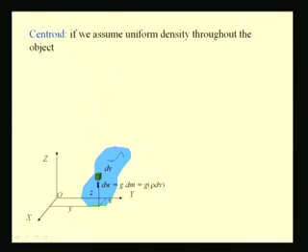So, if we assume that the body is constituted with uniform density material, then this rho can be taken out of this integration and cancelled, and thus we have the volume of the body as integral over the volume dV, the differential volume of these elements, and the coordinates of the first moment are x bar V is equal to integral over V x dV.